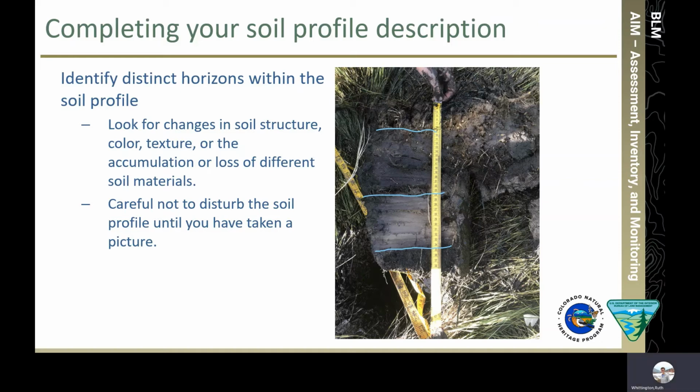Tearing away pieces of the soil from the underside of the core can help accurately place the horizon's boundaries if you've not yet taken a picture. After determining the horizon boundaries on the soil core, it can be helpful to check these depth measurements against the horizon seen inside the pit in case the soil core became compacted during excavation.